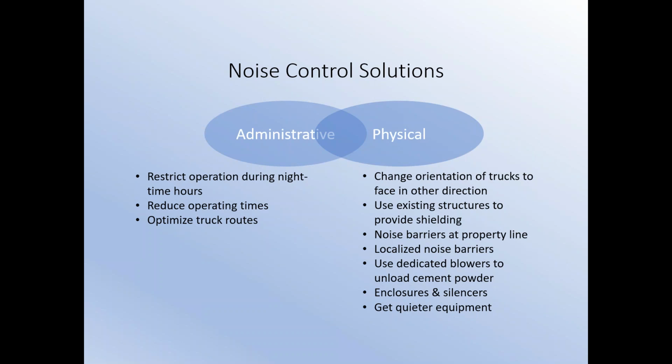So sometimes you can just turn the truck in another direction, and that's going to solve your issue. If that is impossible, you can try to hide the truck behind existing structures, or in other cases, you will need to build noise barriers, either at the property line, or sometimes very close to the actual loading positions, which in some cases can be quite challenging, because it's going to affect the trucking flows within the site itself.